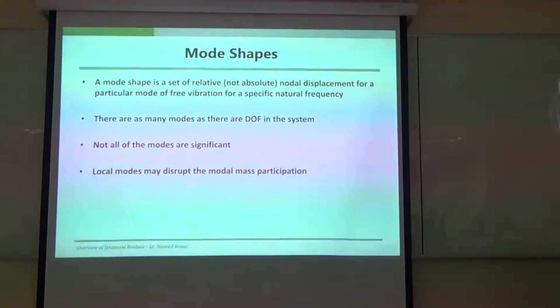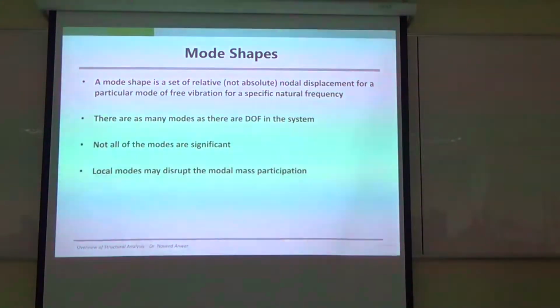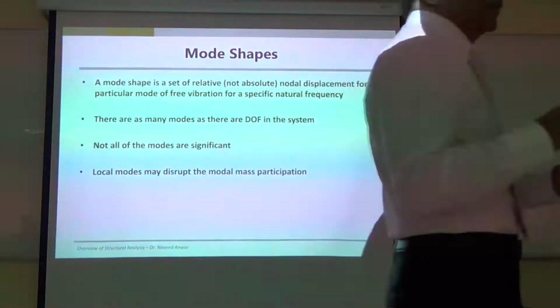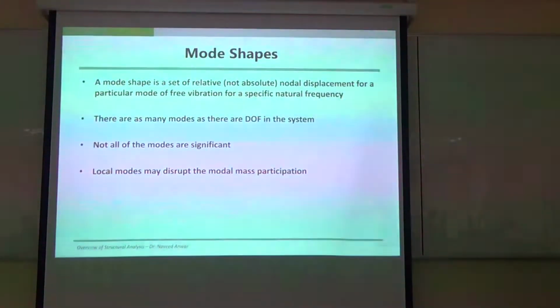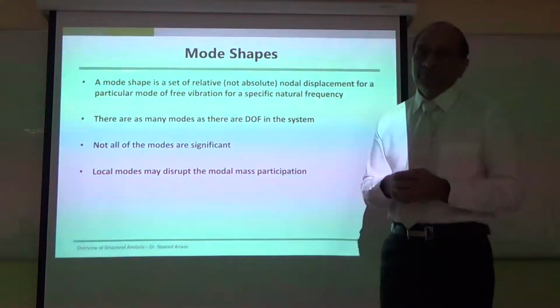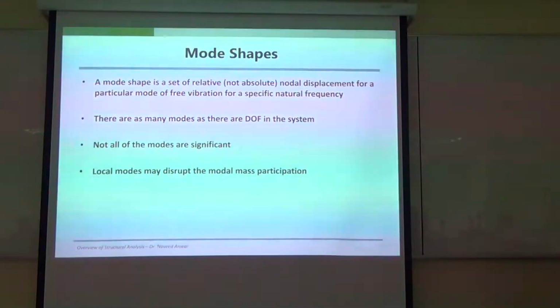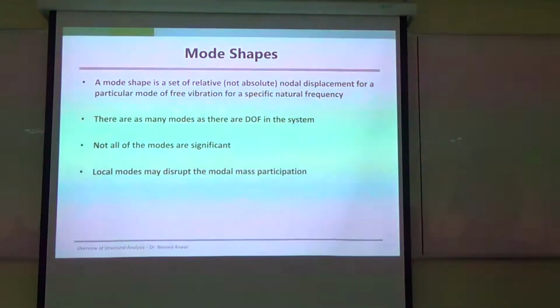For example, do we have a long ruler? Long, yes, thank you. This one. I'm sure Dr. Penning is showing you those, his table, he likes to show those. Anyway, so this is the first mode of this one. So it's the weakest direction. But if I say I won't let you move here, then it will start to move like that, second mode. And then if I prevent here, it will become the third mode. So depending upon how you prevent each mode, it will go to the next mode. And the total response of the building is the sum of all the modes, right? We will talk about that when we go to seismic.